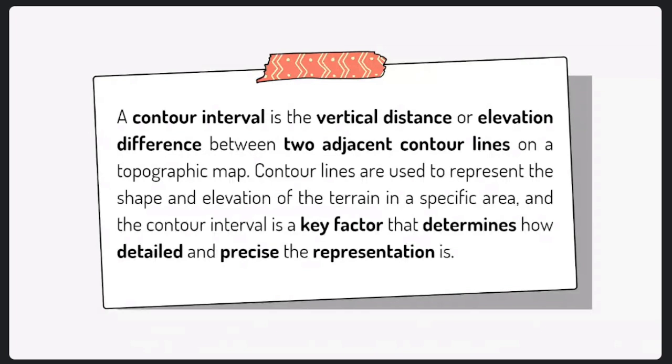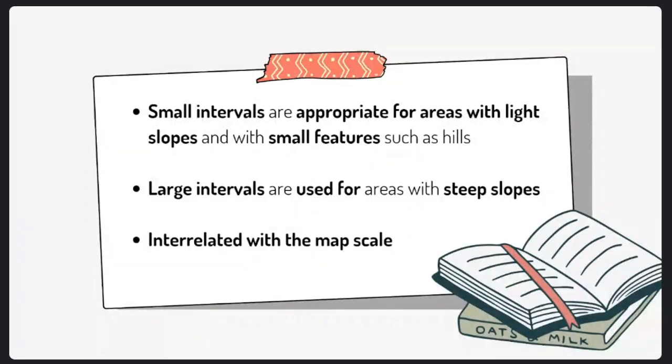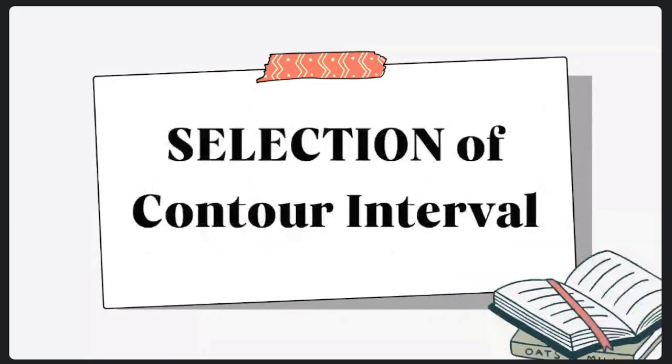Large intervals are used for areas with steep slopes. Usually, the larger the scale, the smaller the interval, and the smaller the scale, the larger the interval. Since we have talked about the contour interval, let us now identify its selection.